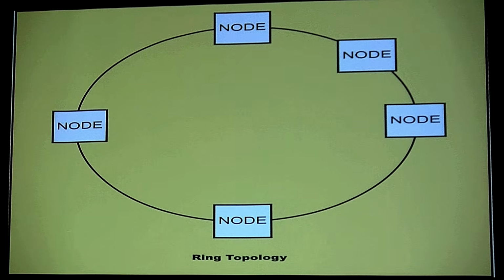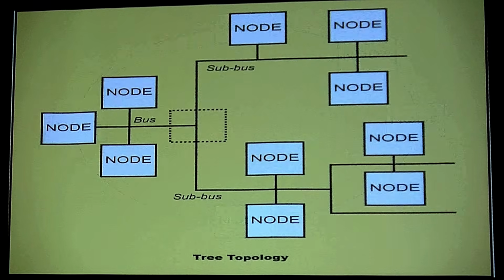So the way that we would make this is we would do something different. I would have a transceiver on this end and a transceiver on this end. A transceiver on this end, a transceiver on this. That's double the amount of transceivers per module. This gets very expensive. If you didn't isolate each section in your ring, if it came down, you pull the whole system down. So this is a more expensive thing. This is like most buses, right? It's expensive. It's not a cheap bus to make. So this isn't something that's generally implemented in most of the cars unless you have some kind of a high-end vehicle, just because of the cost factor that it takes to make it.